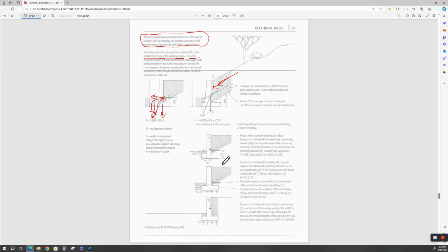This is the centroid, the center of gravity of this whole mess. The rule of thumb is 1/3 the height for this. That means the force from this stuff back behind it is going to want to push it at that point, which means it wants to flip it. It wants to make it go this direction.